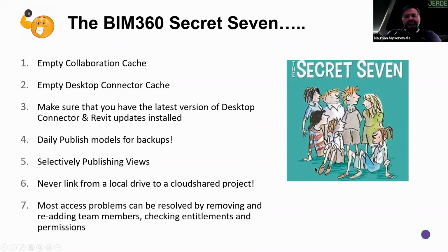Meaning that if you don't publish them daily or whenever you make a change, in Revit you will not be able to download an older version. The only option Revit gives you is to revert back to an older version that was however many saves ago, and you lose all the forward changes. So this way you can download an older version from BIM360 web docs,